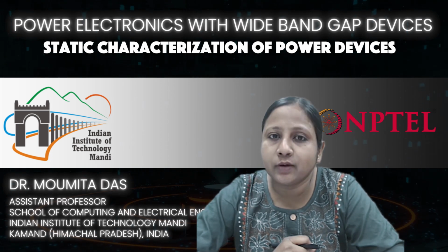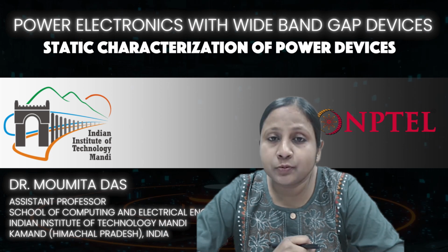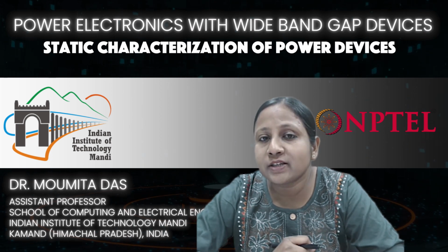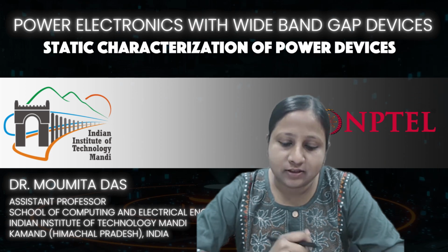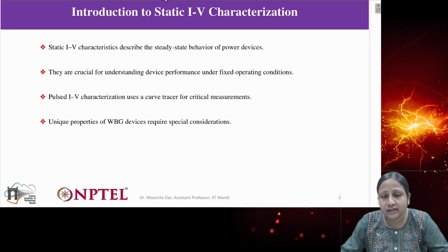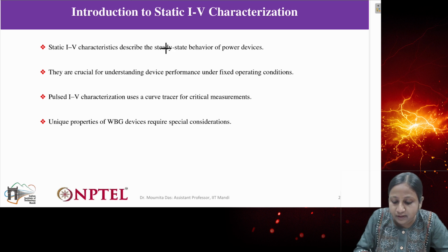of any particular device. In this process we have to provide a pulsed kind of signal in order to get the static characteristics. Basically the static characteristics give us the IV characteristics of the device. So what are these IV characteristics? Basically they describe the steady state behavior.